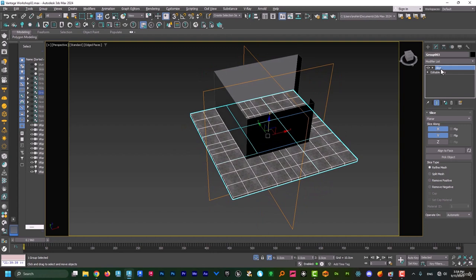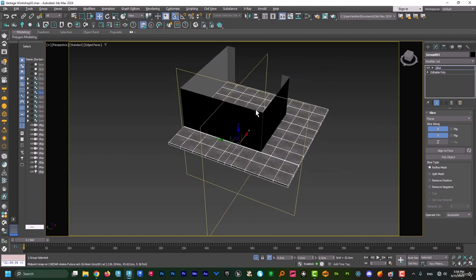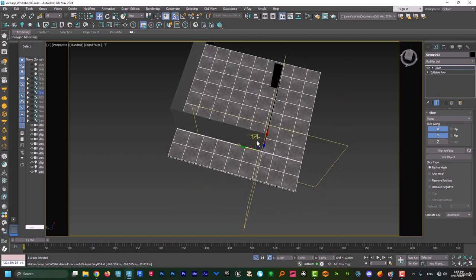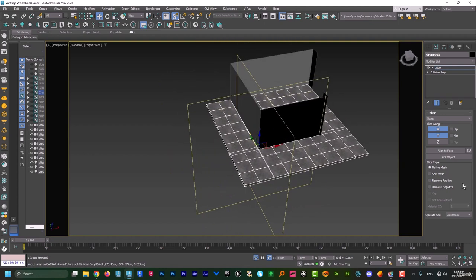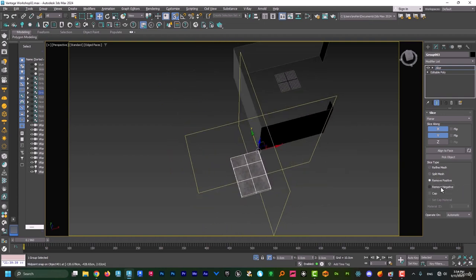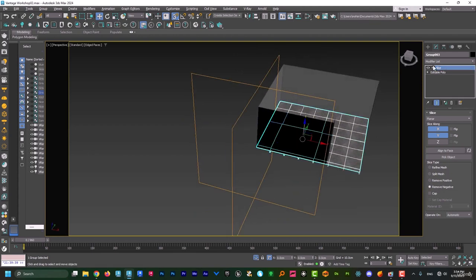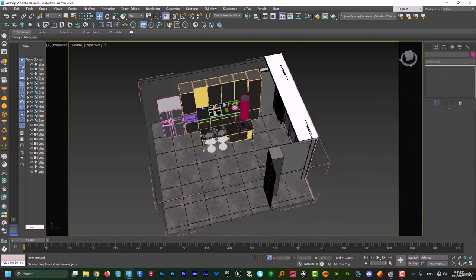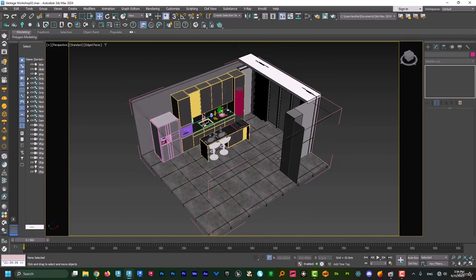Now I activate this slice once, and then we hit S and we bring this here, and then come here to this wall. And right now I command remove positive, and again remove negative. Easy like that. Simple as that. With one modify slicer, I did both. So we are done. We should get to importing objects.